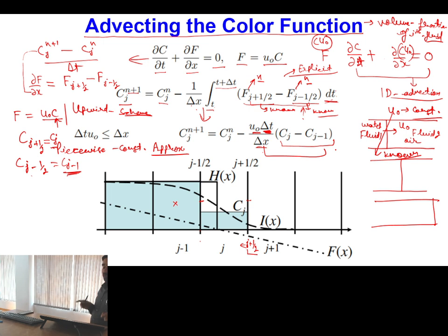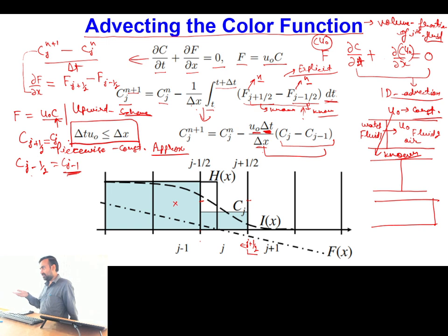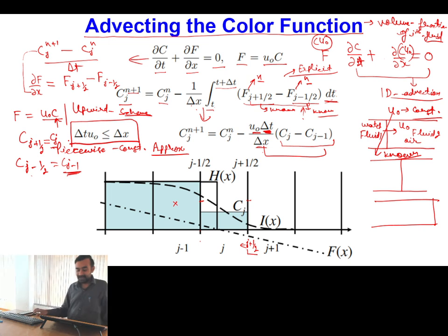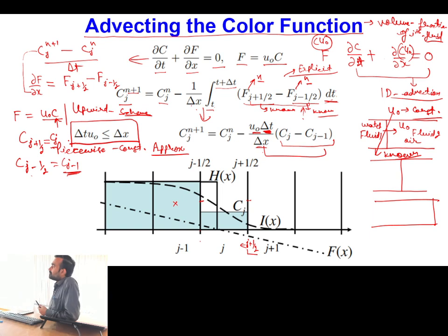Now, one important point you need to keep in mind: whenever we solve the interface advection schemes, whenever we numerically solve the equation, I have already told you during the solution of the scalar transport equation as well, that an explicit scheme becomes unstable at large values of delta t. So delta t we have to limit by a certain condition in order to have a stable solution from an explicit scheme. Is this point clear?